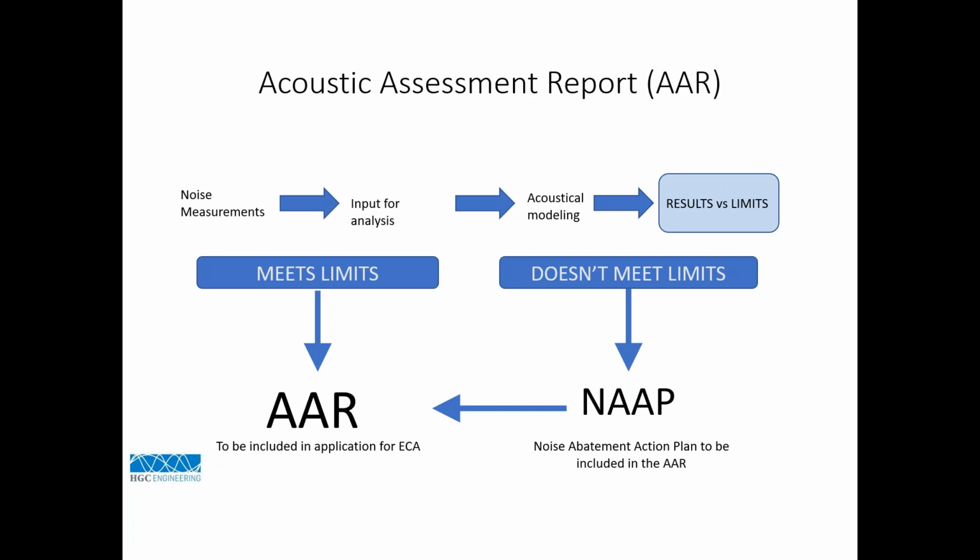And all this information they're going to then use together with the measurements to build an acoustical model and to come up with results. Essentially, the results then reflect the sound levels from your site at the nearest, typically residential, homes or any other noise sensitive land, which can include a hospital or child care center and so on. And in most cases, it's going to be some sort of a residential dwelling.